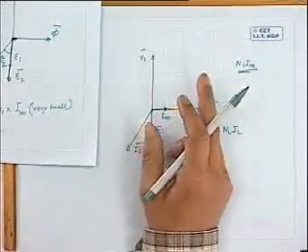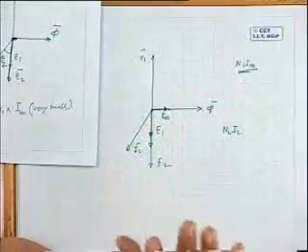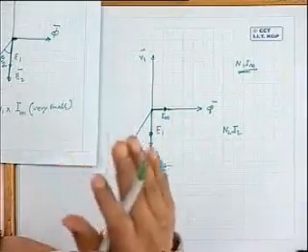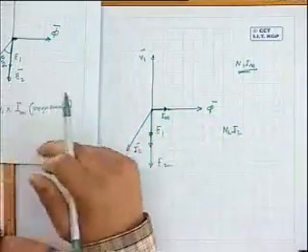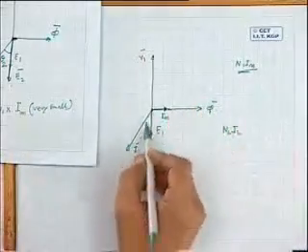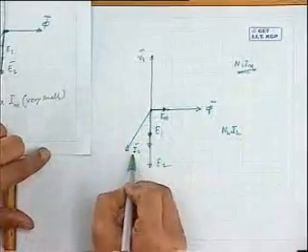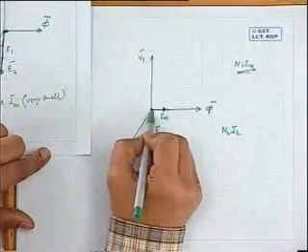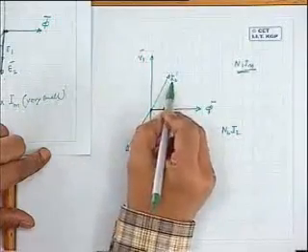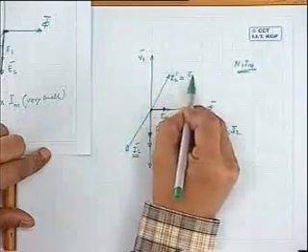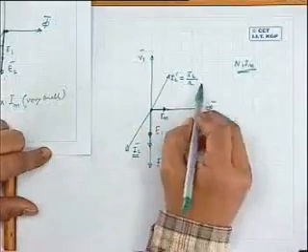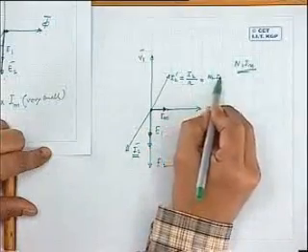That is, in this diagram, if I show it, it should be like this. I2 will be there. So I2 and I1 will be in time phase. Let I2 go on increasing, I1 will also increase. Let I2 come to 0, I1, the current reflected from the secondary onto the primary because of the secondary current, will also go to 0. So this is shown in the phasor diagram in this way. Suppose this is I2. Now the primary will draw extra current, I2 dashed, whose magnitude will be I2 by A.